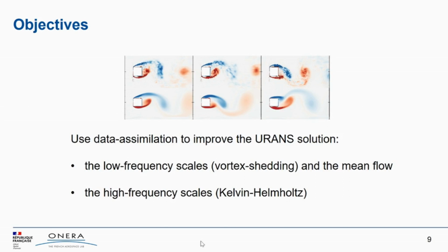There are various methods in the literature to perform that kind of data assimilation. And we have mentioned here three kinds of methods, three kinds that we have also investigated in the last year. So the first one, the main kind of method, is the variational method. And it basically consists in minimizing functional objectives that represent the error between the output of the numerical model and the data. And there's a physical constraint that the output satisfies the numerical model, which are usually physical equations. And to minimize that functional objective, we play on initial or boundary conditions.